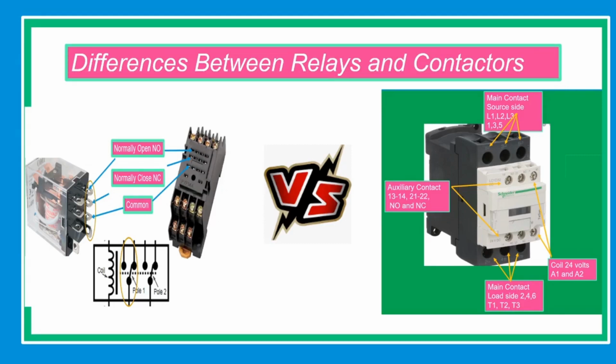Our tutorial for today is: what is the difference between a relay and a contactor? Relay and contactor have the same function of switching a circuit. From the application point of view, you see magnetic contactors placed inside an electrical cabinet, while relays are used in low voltage applications such as alarms and pilot lights. Both share the same function, electromagnetic switching, and operate under the same principle.